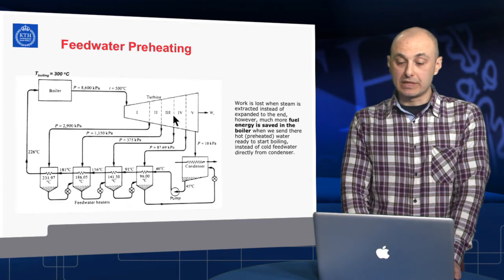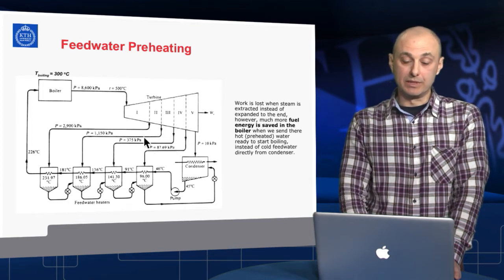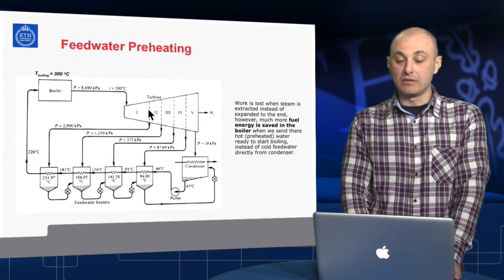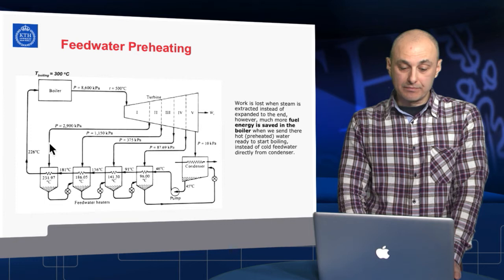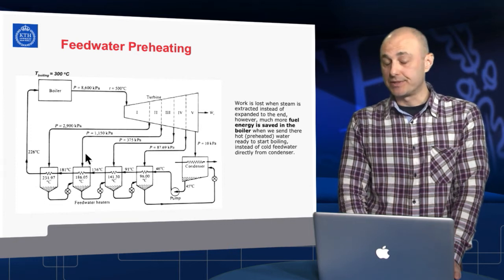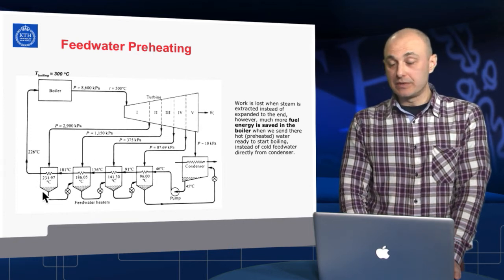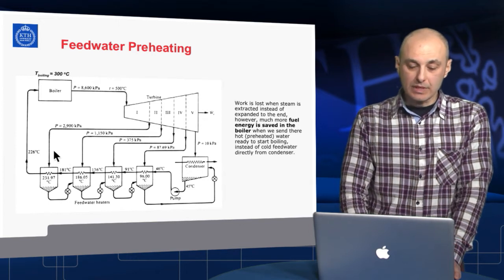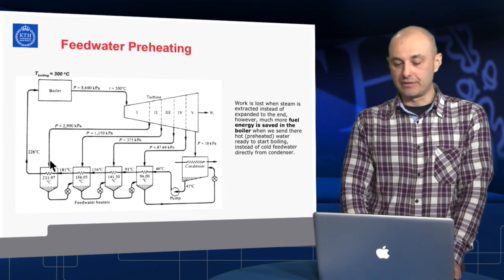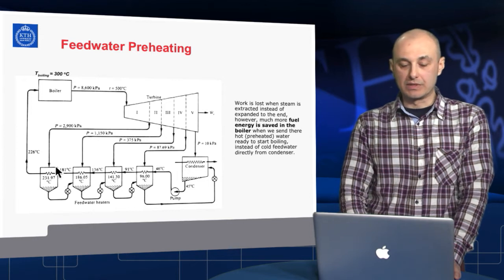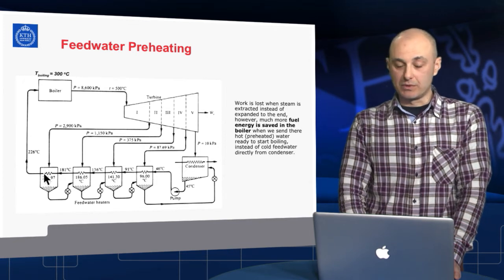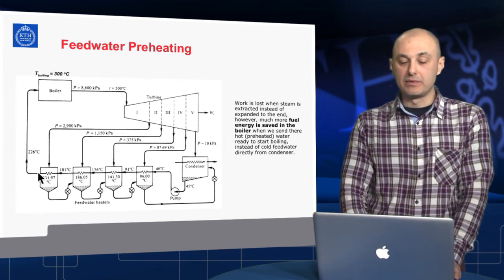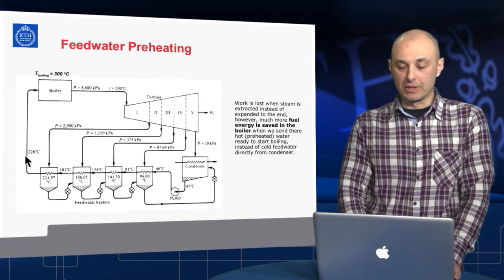It involves extracting steam from the steam turbine, usually called bleeding points, and sending that steam into heat exchangers. The steam condenses, giving the large latent heat involved in the condensation process back to the liquid water. The main feedwater line in terms of liquid water is being heated up a bit before it reaches the boiler.